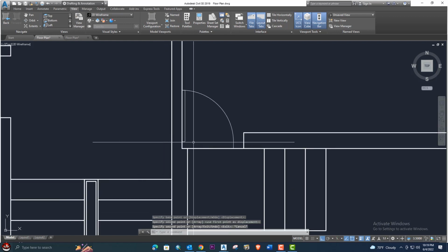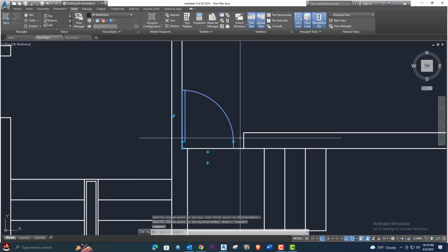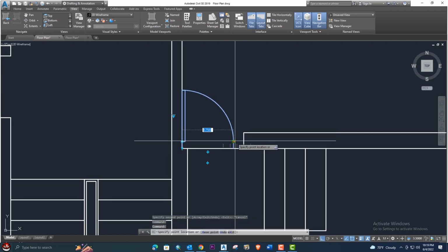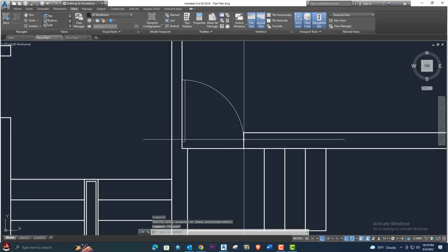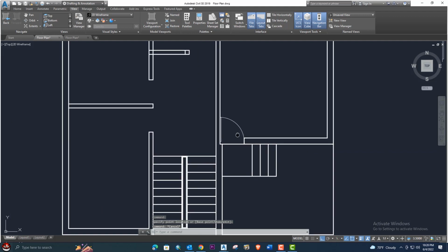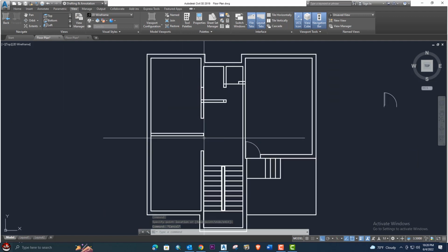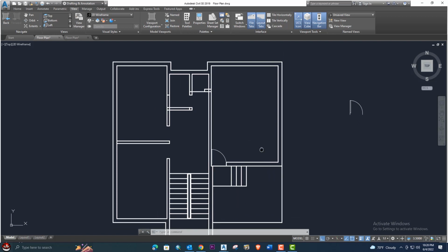Once you select this door, you can cover this free space because the block works automatically for 0.9. It works for 1 meter even, you can see here 1 meter, and it can also work for 0.6. It's a custom block. Let's drag it here. Now it's okay, and you can easily place these doors here. Select and mirror the doors.